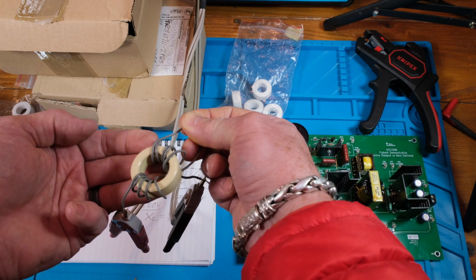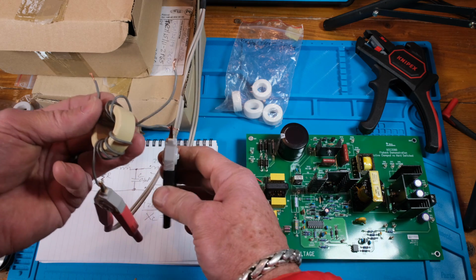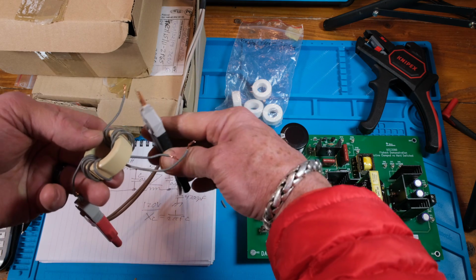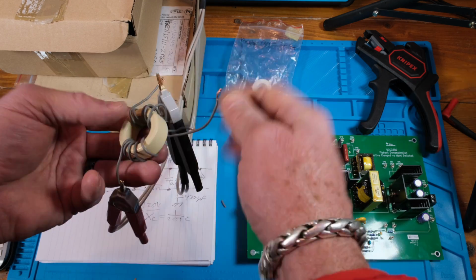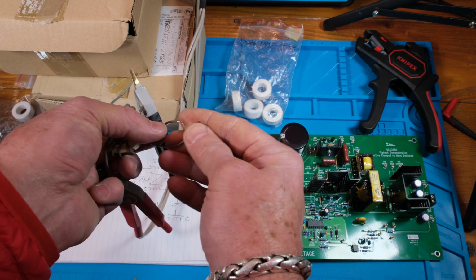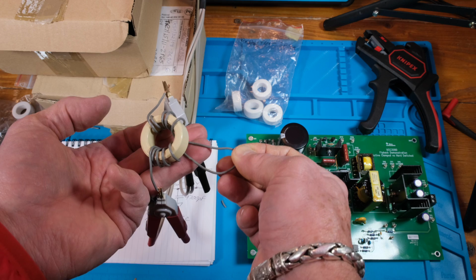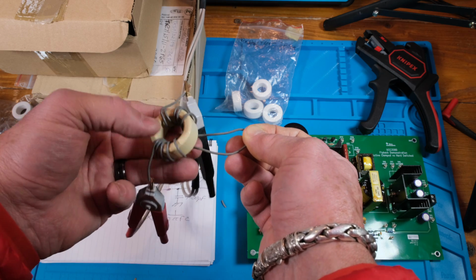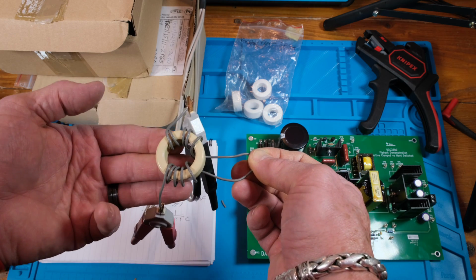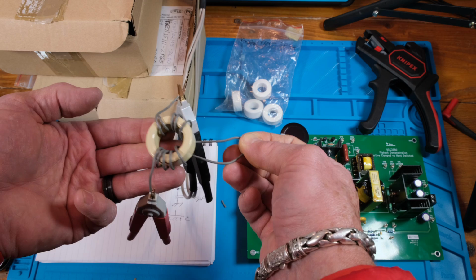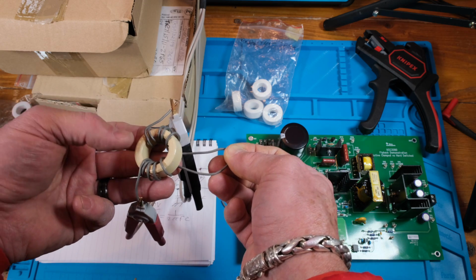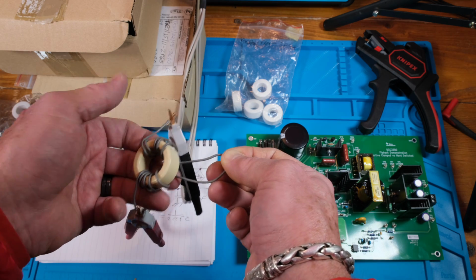So 2.4 millihenries, okay? Now if I go to the other side of this coil on this side, and I take these 2, now I'm back at 2 microhenries. So now this field's canceling with that field, okay? And that's the differential mode. So I think I might have called the other one differential. The other one is common mode.